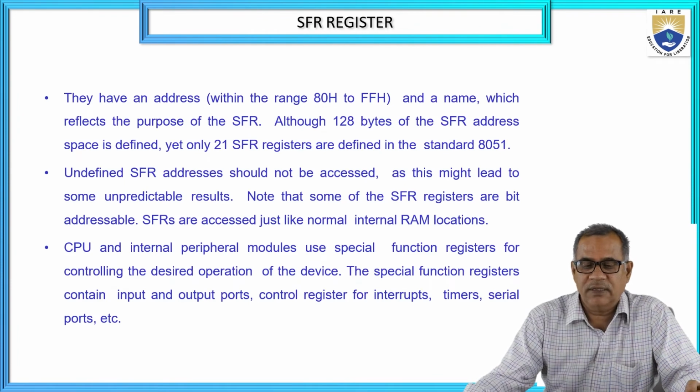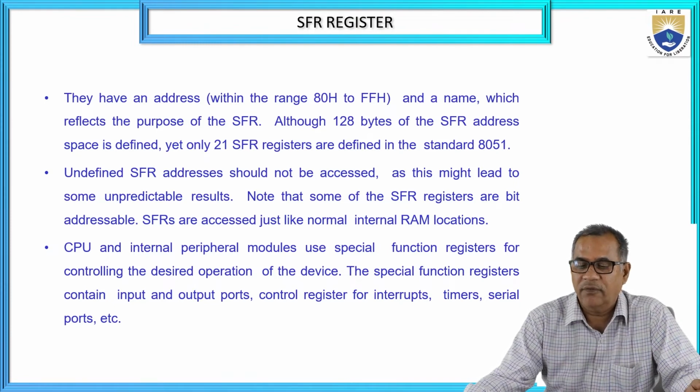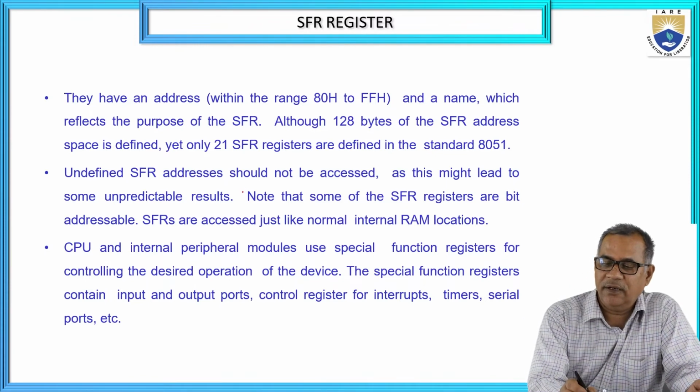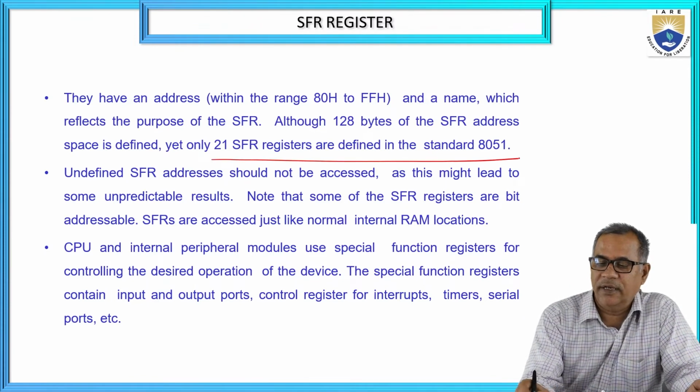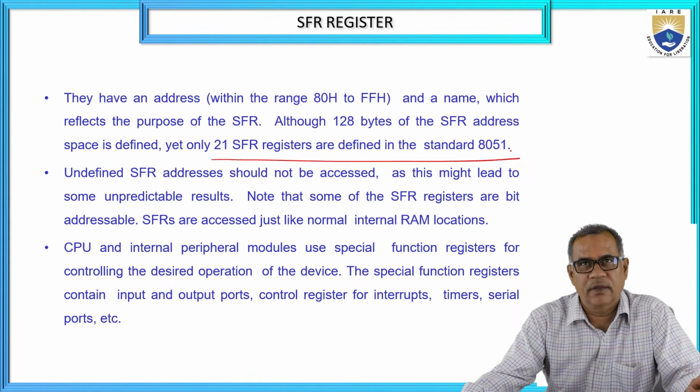So these SFRs have the address in the range 80H to FFH, and the name of it reflects the purpose of the SFR. Though there are 128 bytes of SFR, only 21 SFRs are used in the 8051 microcontroller.